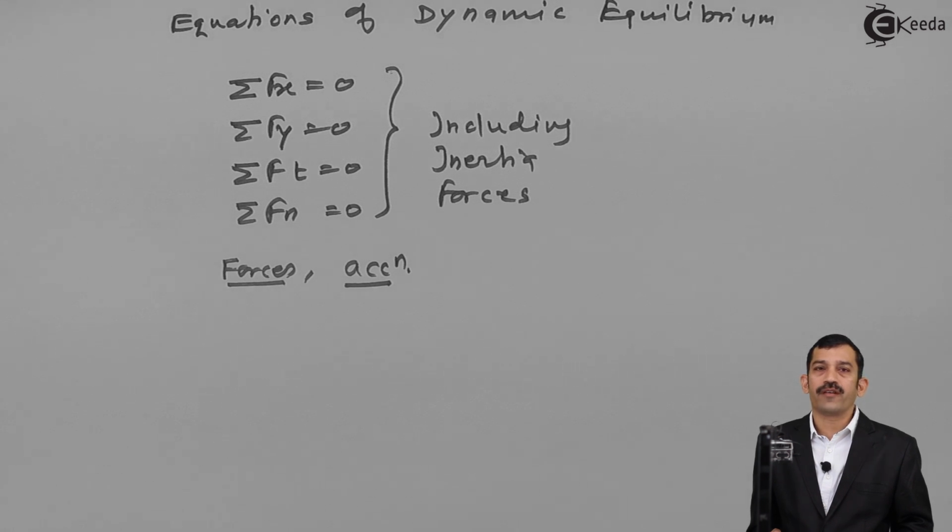Once we will draw free body diagram, in that one which includes what? Any external force which is acting, weights of the bodies, normal reaction. Then from magnitude and direction of forces we will decide resultant force acts in which direction. The resultant force acts in some direction, the acceleration of block must be in same direction as per Newton's law. We will represent that direction of acceleration by dotted line because it's not a force.